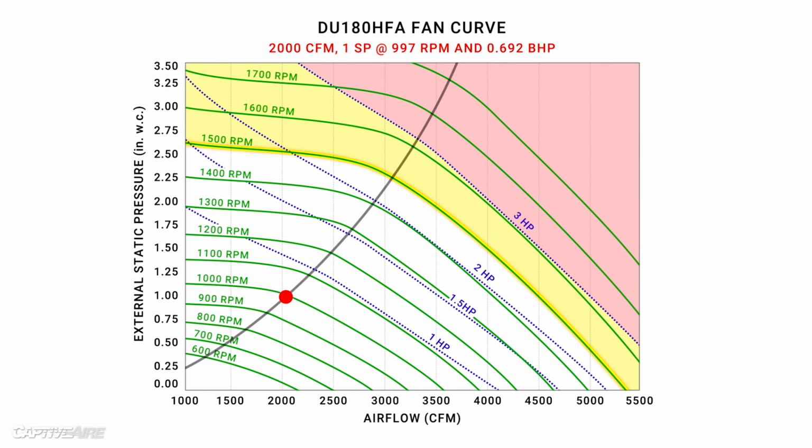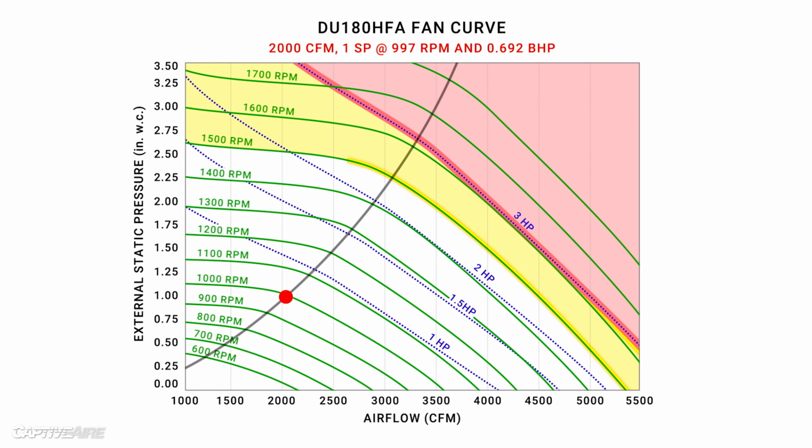So we've got this entire area here, which is yellow. I like to refer to that area as kind of like the warning track, like in baseball. We allow people to select in that range, but we don't recommend going into that range or above that range, just because once you start getting to that range, you're very, very close to the maximum output that fan can perform. So it doesn't really leave you with much adjustment in the field.